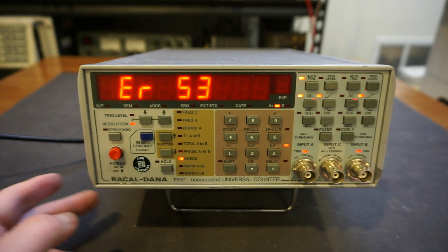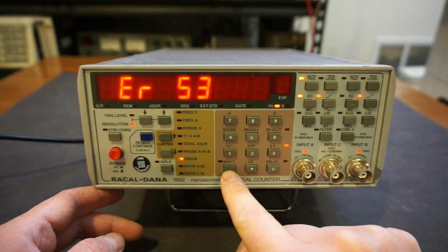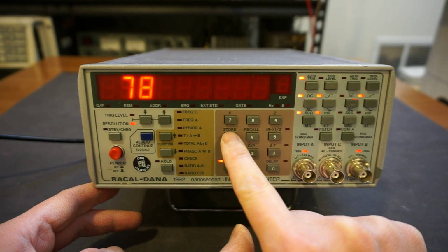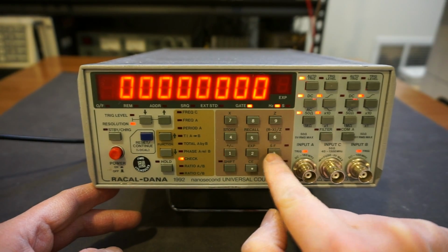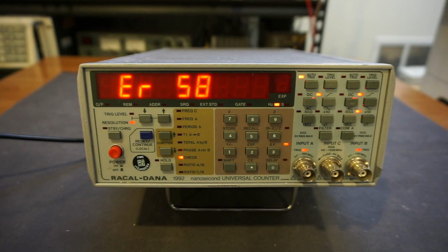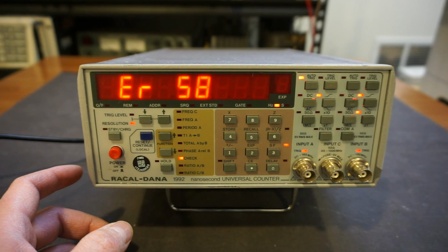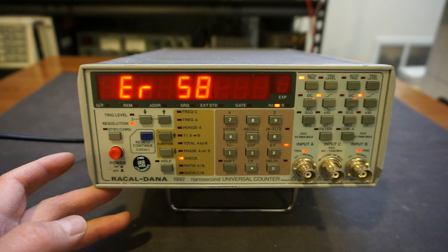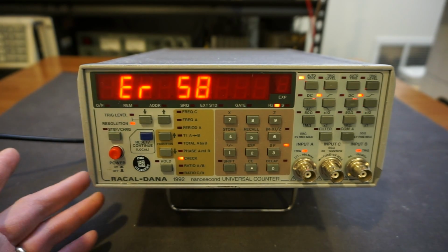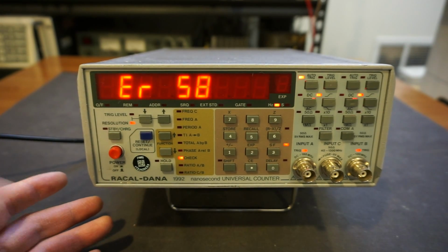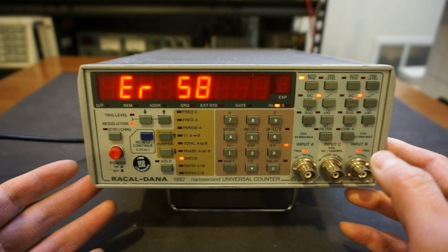And then the same thing happens if I run for the other channel. So let's just get it out of here. 78, shift, store, SF, shift, SF. So again, as you can see, we have error code 56 and 58. Now, if you look at those error codes, those suggest that there's something wrong with either the amplifier or the relays of these two channels, and it didn't really give a lot of information. But nevertheless, clearly something is wrong with these two channels.